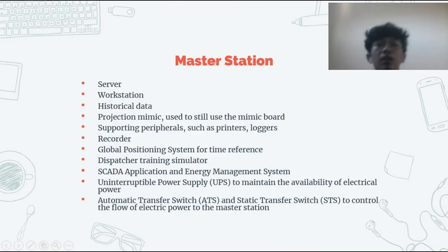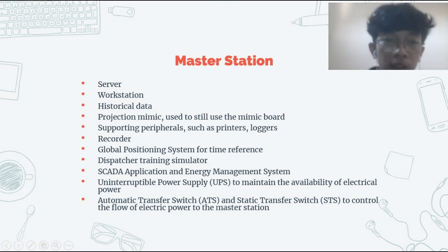Next, master station. This is a master station. Server, workstation, historical data, project mimic, which used to still use the mimic board, working peripherals such as printer and logger, recorder, global positioning system for time reference, dispatcher training simulator, SCADA application and energy management system, uninterruptible power supply or UPS to maintain the availability of electrical power.